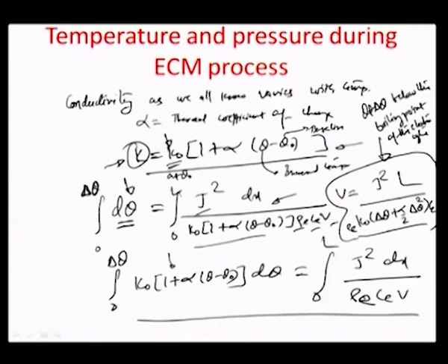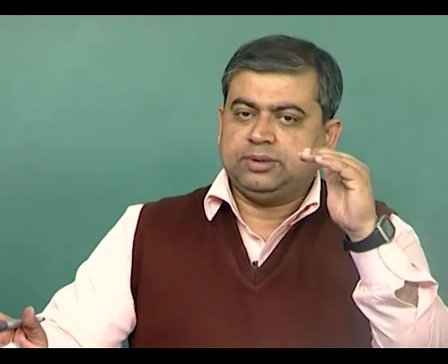So, in summary, what we have really tried to see is that there is an electrolyte flowing between a tool and a workpiece, and there is a heat flow by virtue of the electrical power that is added to the system, from one end of the equilibrium gap to the other end. The velocity of flow is really dependent on a lot of parameters, because if we want to keep the constraint that the electrolyte does not boil off before it goes to the other end, it should be able to transfer the power that is pumped in from the electrical system into the electrolyte without changing its temperature so much that it goes above the boiling point.